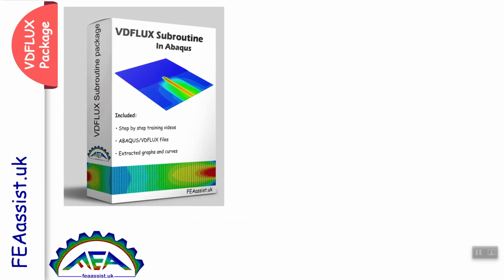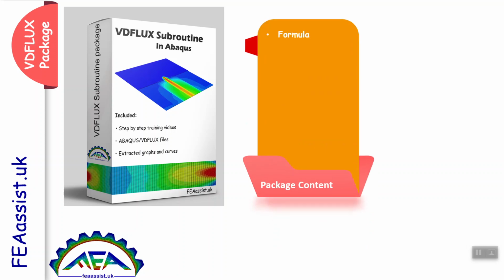We have prepared a training package for you, which is the VUFLUX subroutine in Abaqus. In this package, the formulation, the heat transfer, the mass transfer, and the mass diffusion formulations are explained. The VUFLUX subroutine variables are all explained.